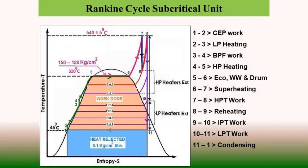There are further extractions from the intermediate pressure turbine exhaust to the LP turbine crossover. From there the next extraction is taken and goes to the boiler feed water tank and feed water heater, which is an open heater, the only open heater in this system.